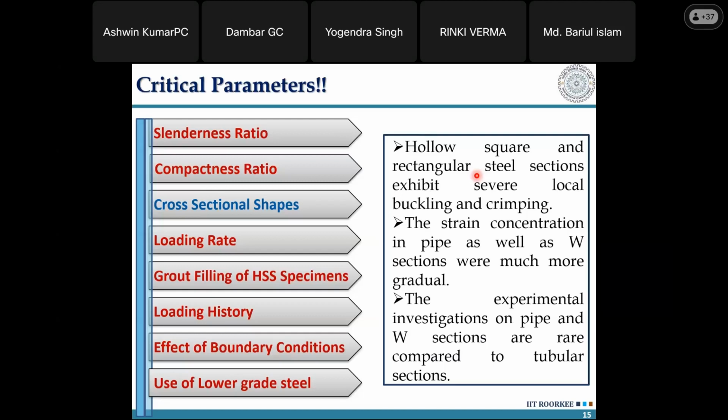But the problem is the connection becomes a bigger problem in terms of I sections. The second best are hollow circular sections, where the only problem is how to locate the center at one end. That is okay. If you cut a slit at one end, let's say everything is well and fine. But when you cut the slit at the other end, if you are using no extra gadgets or any laser type of equipment, and you are doing it at site, the most probable condition you would end up with would be an eccentricity in the loading. You may cut a slit at one end, but getting an accurate, inline slit at the other end of the brace will become a problem in terms of circular sections.